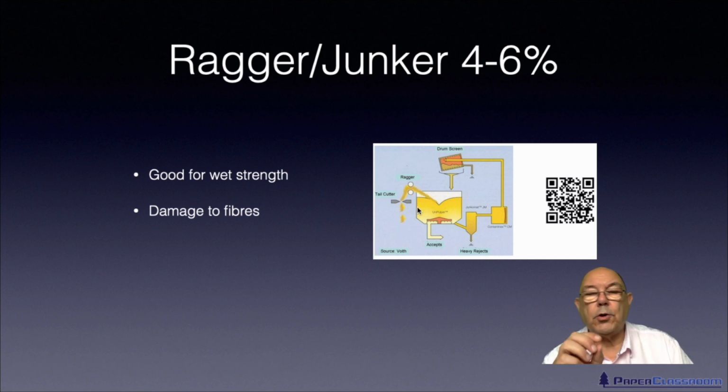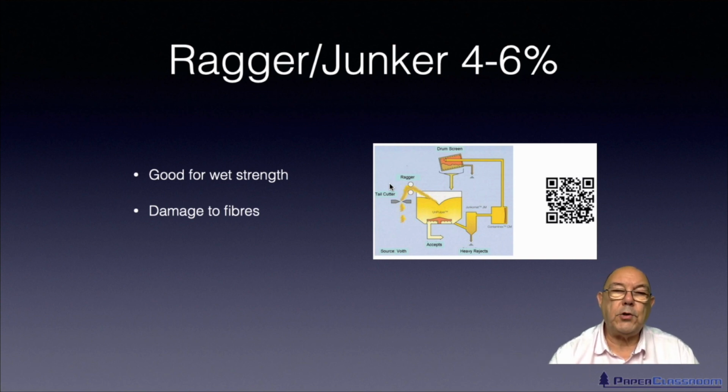So that's the advantage. So with the worst quality waste, at every opportunity, you take the chance to improve the quality by removing some contamination. And here, even at this first stage, even when you're only just dispersing the fibres, you're using the opportunity to remove contamination. So, sort of biggish pieces of flexible packaging will get caught in those wires and go out. Underneath the rotor, the base is perforated. So as the fibres do get dispersed, they will be sucked out through there and carry on to the next stage.